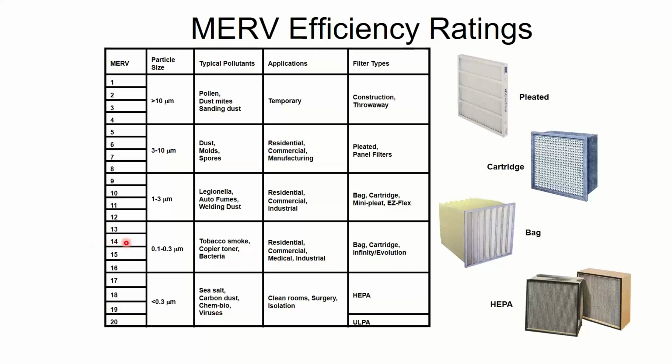And then it said if you can't do that for size and or pressure reasons, then at least get a MERV 13. It was kind of weird that they gave you two options. They're basically saying MERV 14 is what you kind of need, but if you can't do that, MERV 13 is decent. It helps. Anything below MERV 13 is pretty much doing almost nothing for virus control. So if you're getting a MERV 10, 11, 12, it doesn't do much.